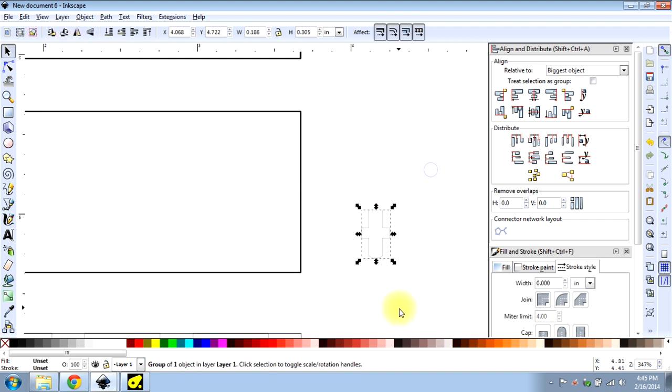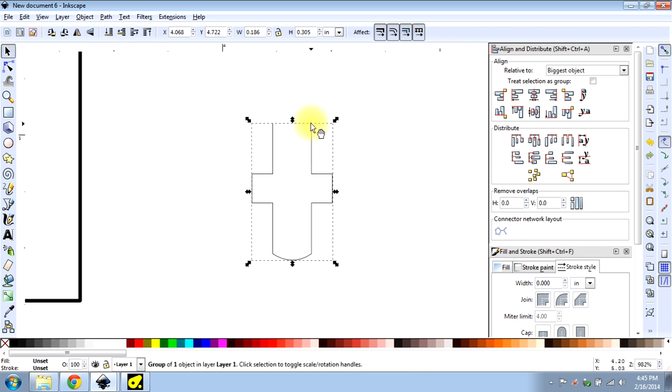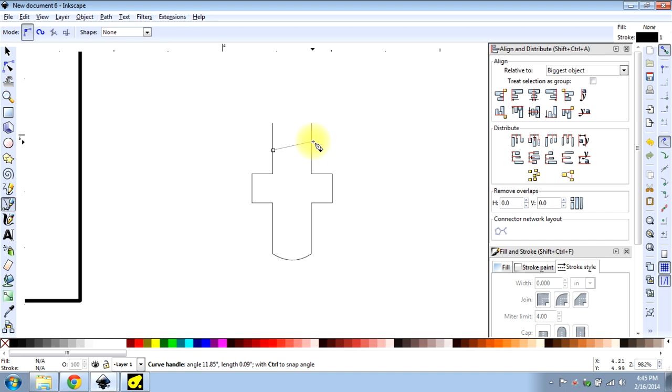All right, this guy right here. This is the cutout for the screw that's going to fasten these panels. And this will make more sense in a second. This here, let me grab a pen so I can see. This here, that is the width of your screw, the diameter of the screw. From here to here, that is the length of your screw plus a little bit minus the thickness of your plastic or your material. So in this case, it would be the length of the screw minus 0.12 for the thickness of the plastic plus 50 thousandths longer for the tip of the screw.